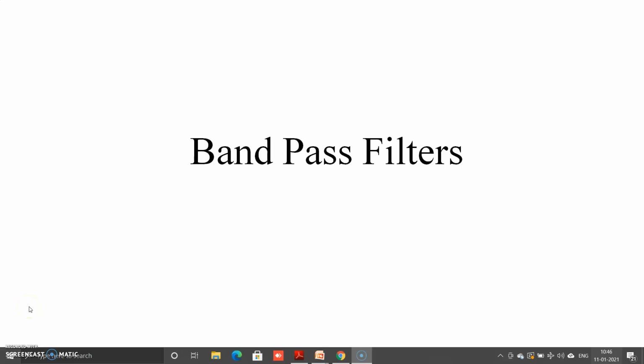Welcome to this video. Today we are going to discuss bandpass filters. We can define a bandpass filter as a filter which has a pass band between two cutoff frequencies FH and FL, such that FH is always greater than FL, that is, the upper cutoff frequency is greater than the lower cutoff frequency.